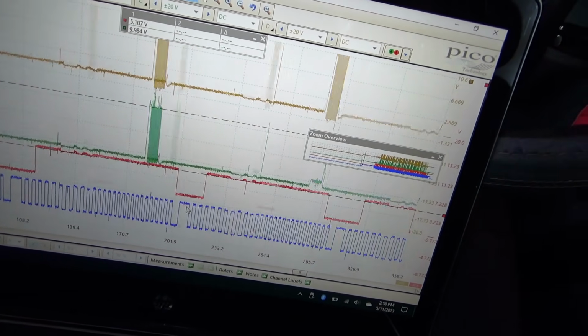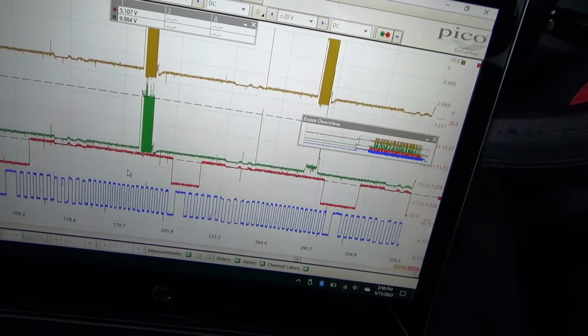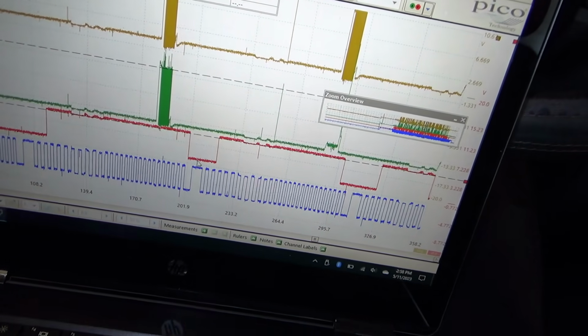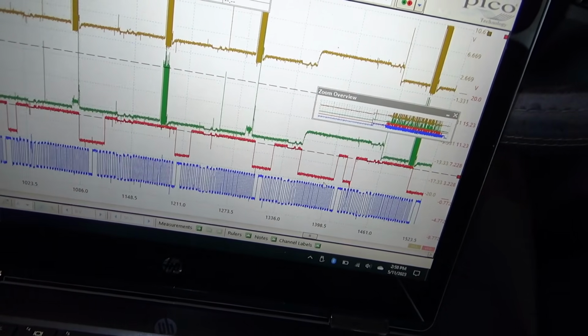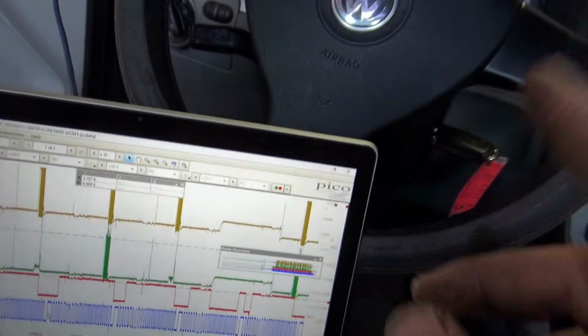Still setting a 341. So whenever you're close, it sets a 341. Whenever you're really far off, it'll set a 3008, I believe. So we just want to advance it a hair, so all of the sync notches are within the cam pulses. So I just did that.